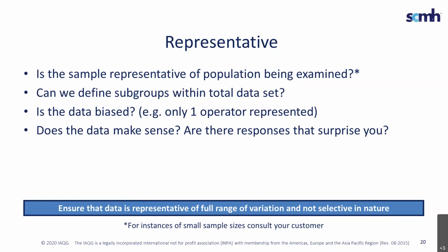If we truly want to understand the process capability, the first question we need to ask ourselves is, how many samples, and what number of samples, make it representative of the actual process? Now, there's a little asterisk here because a lot of our customers will actually have specifications or qualifications for a representative sample size, so you may want to consult your customer.